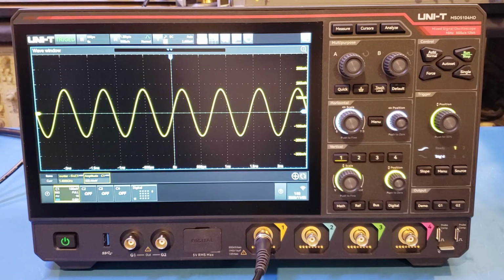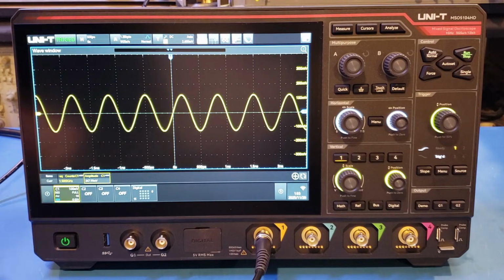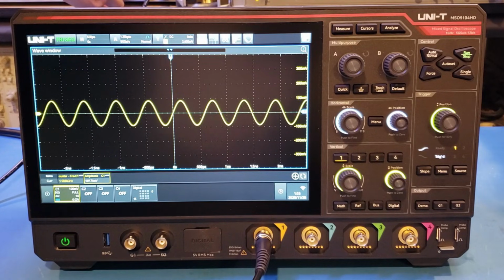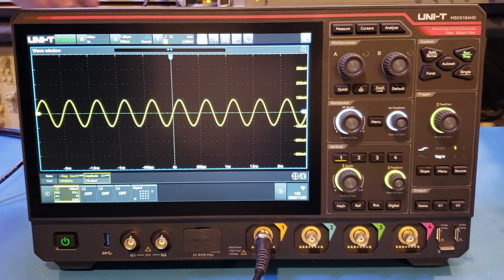Now let me keep increasing the frequency and just to see what we get on the scope. Of course, it's already below the 3 dB bandwidth, but we should be able to see whether or not we're actually able to capture that signal. Given the 5 gigasamples per second sampling rate, we should be able to capture quite a bit higher. So let's take a look. So now I'm doing 1.5 gigahertz. And you can see we have no problem detecting that 1.5. The amplitude, of course, dropped quite a bit. So 1.6, 1.7, 1.8, 1.9, 2 gigahertz.